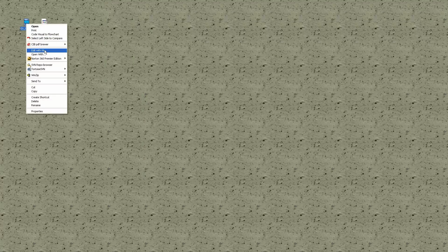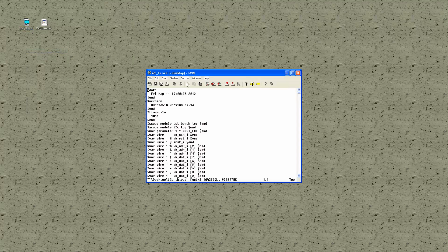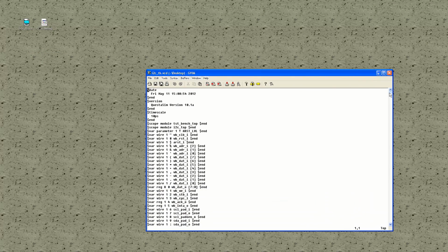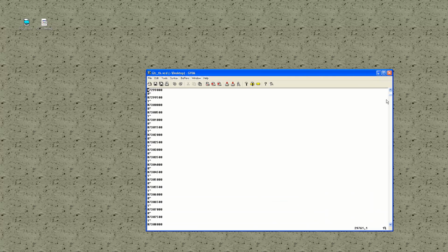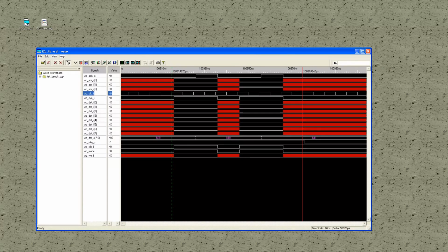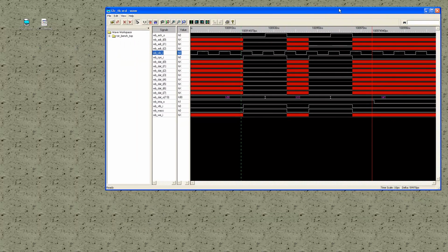I'll open this with Vim. You can see it's a standard VCD file. Variables here, and then your simulation text below. So if I open this file again, here you see the simulation, and what I want to do is capture the area between the green cursor and the red cursor, and I want to capture the following signals you see here on the left side of the diagram, which is basically the wishbone interface. So I'm capturing a couple of write cycles from the wishbone interface.